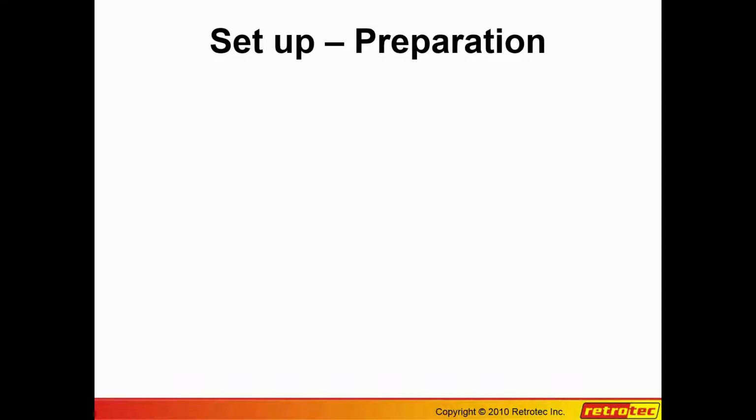In this case, when we're doing air changes at 50 and so on, we're really looking at the performance of the building overall. That means that intentional openings such as HRV vents, exhaust fans, and ventilation openings aren't taken into account, because we're trying to see how tight the building can be under normal operating conditions.